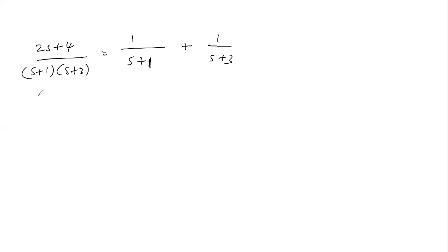So let's assume our region of convergence, sigma, the damping factor, is greater than -1. Now, if it is greater than -1, we can draw that on the s plane. This is j omega, this is sigma, and this is -1. The region of convergence, sigma greater than -1, must exist towards the right, because anything to the right of -1 is greater than -1, isn't it? So it means this is a right-sided signal.